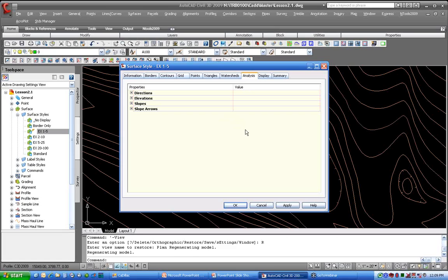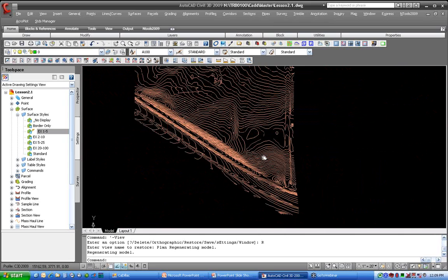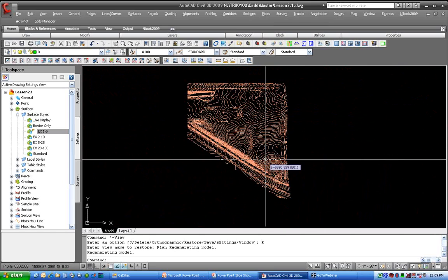And I actually have some styles that we'll bring in a little bit to show you how these are put together. All right, so kind of giving you just the general overview of the styles components and properties here. Main thing you're going to see is that component tab where I can control what you see and what layers those are displayed on.